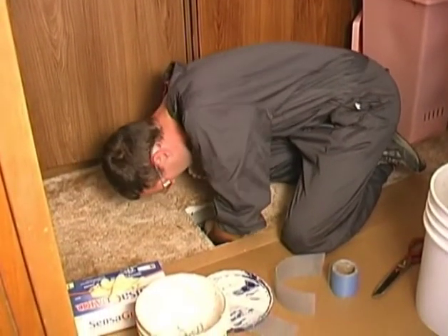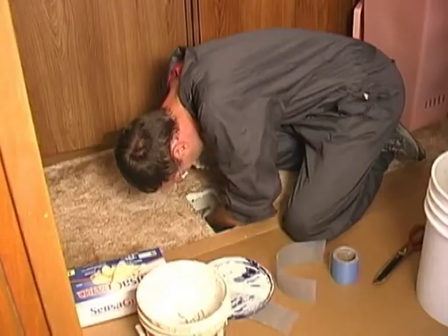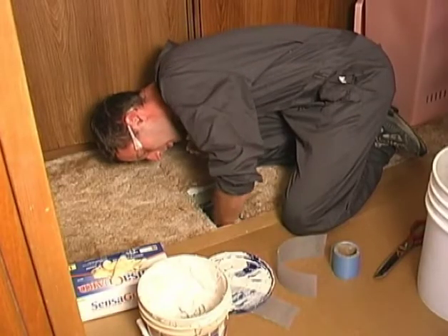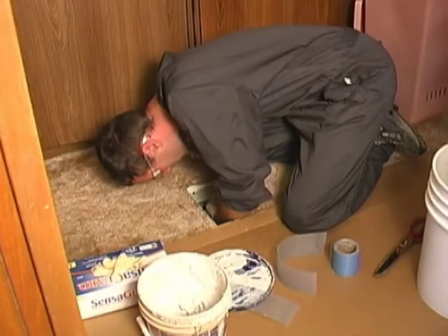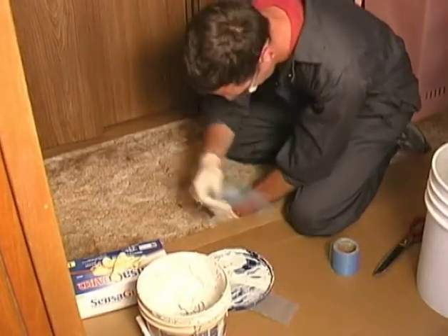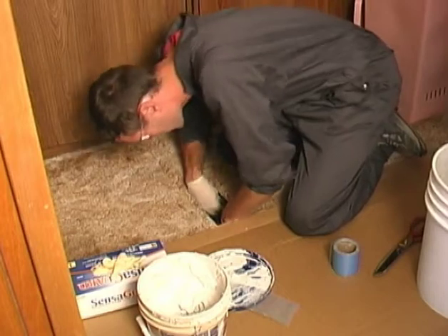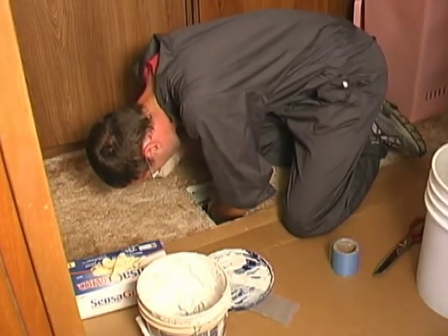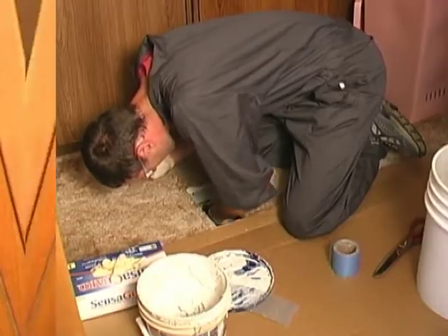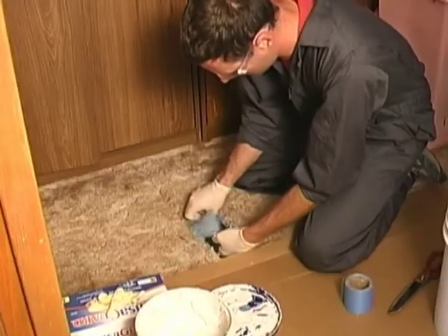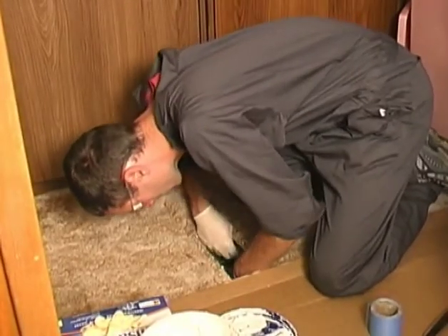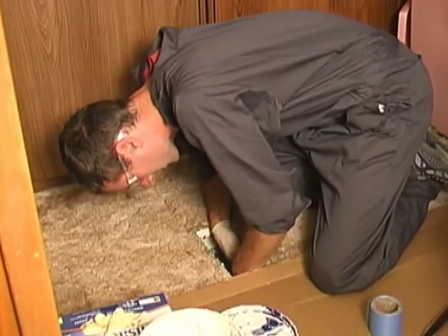If we're unable to reach the end of the trunk line, because often the end of the trunk line runs past the register, maybe by 8 to 10 feet, we can seal the end from underneath, but a quicker way to do it is to put a block right where Ross is, right at the register. It's easier to do that from inside than going underneath the mobile home, opening up the underbelly and fixing the end.